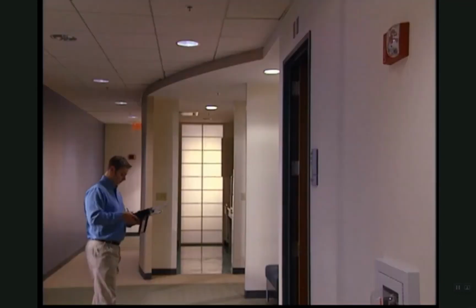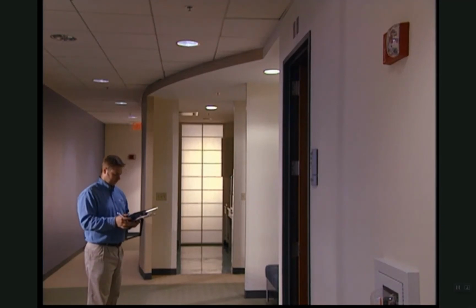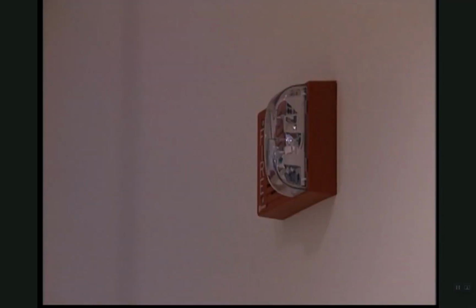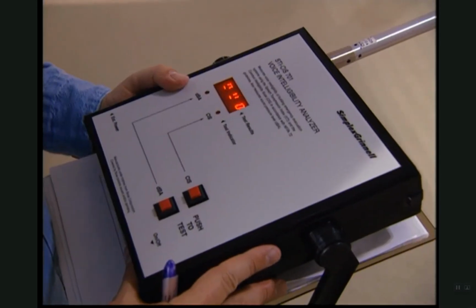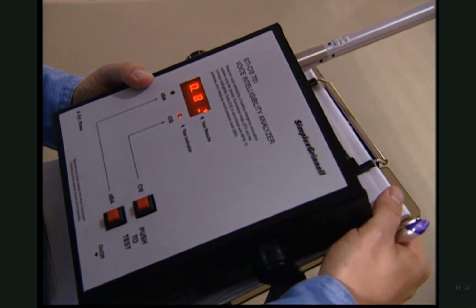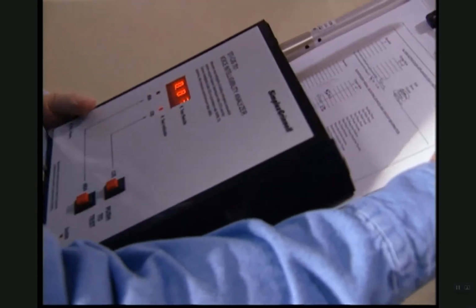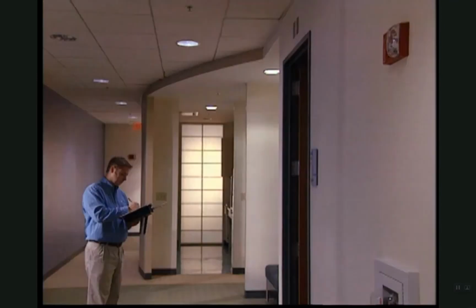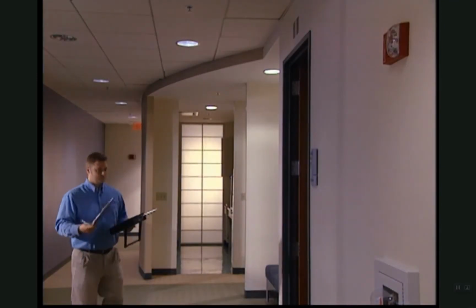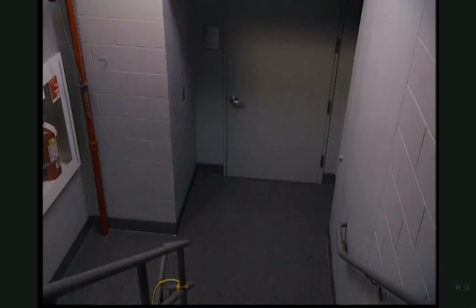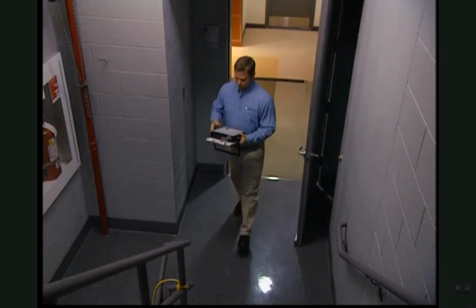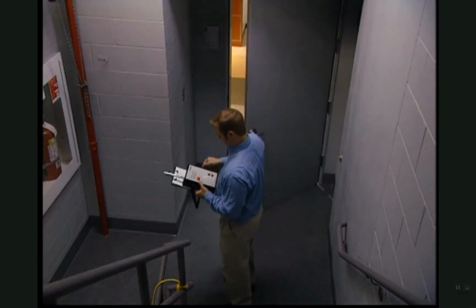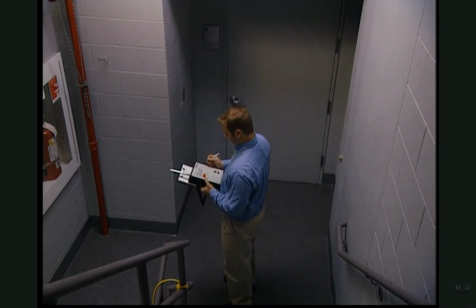To determine intelligibility, you must play a special audio recording of calibration frequencies and analyze the sounds with test instruments. NFPA 72 provides specific guidance for this test. Pay particular attention to sound reflective environments, such as painted concrete block walls, which can have a major effect on the clarity of voice announcements. Check intelligibility in all areas where occupants may be, including conference rooms and out-of-the-way areas.